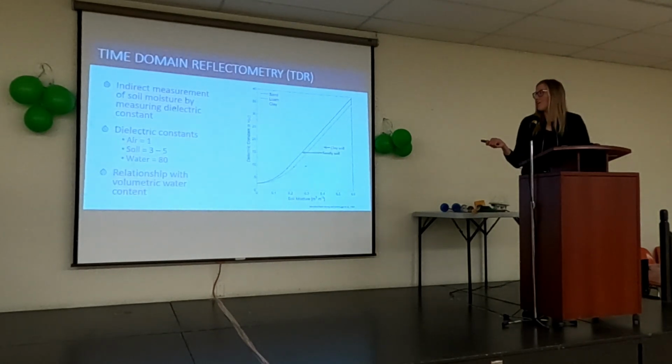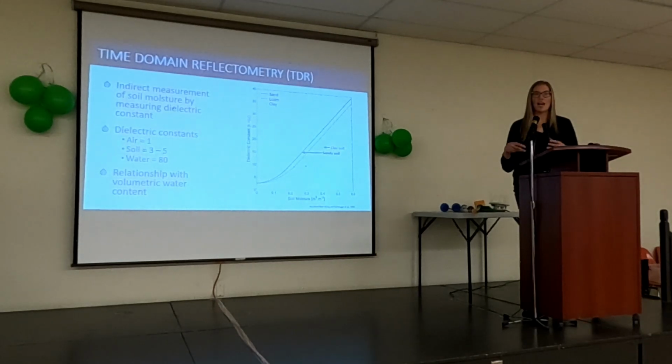And the dielectric constant has a positive relationship with volumetric water content, so as your moisture content goes up, your dielectric constant will as well. And obviously, back to soil texture, whether you're working with a clay or a sandy soil, they're going to have a different calibration curve to deal with.